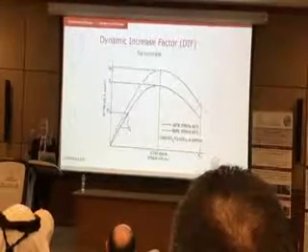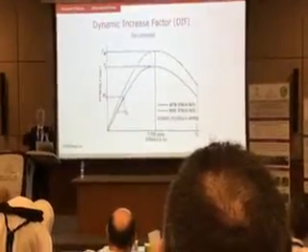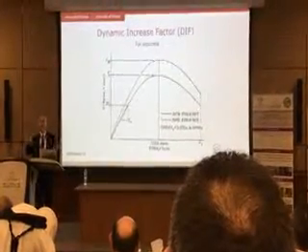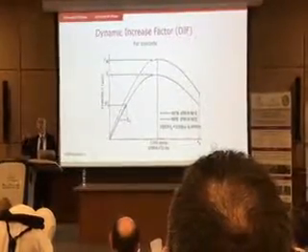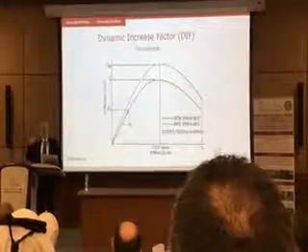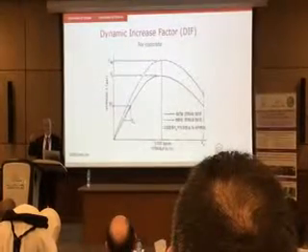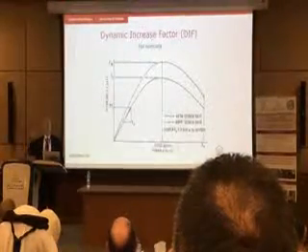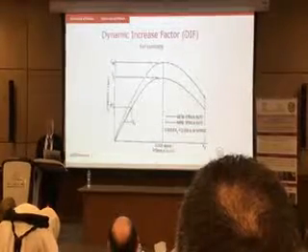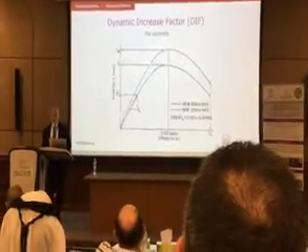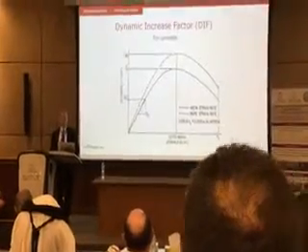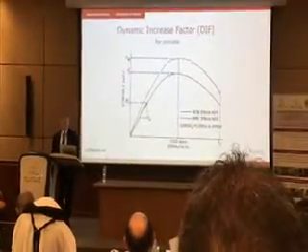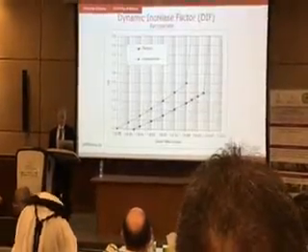It's just milliseconds, you hit, the material is about to fail, but the load is gone. So there is a strain rate effect, and under higher strain rates, materials have higher capacities. So this dashed line is what is accepted by the standard for use in design. This is called the dynamic increase factor.